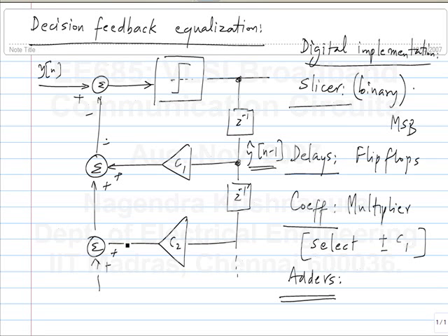Okay. So you have different blocks and there is a constraint on the delay of each of these blocks. Each of these blocks will have a delay when you implement it as a combinational or sequential circuit. And the total delay must be sufficiently small. Depending on what the total delay is, you can clock it at a certain rate.